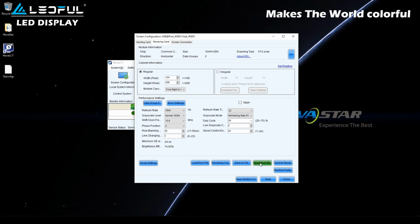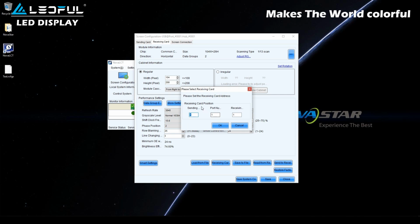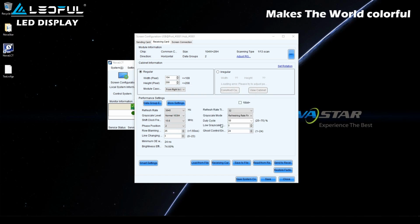3. Click Read from Receiving Card to read back parameters from a receiving card to Nova LCT. For example, the first receiving card is connected to the first Ethernet port of the first sending card. 4. Click Save to save parameters to receiving cards. This can avoid data loss after the screen is powered off.